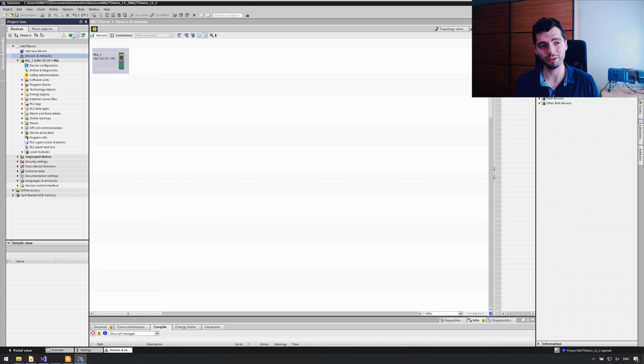But sometimes you will find this icon green with a tiny blue refresh icon. This means that someone made some changes on the project server and your version is no longer up to date, and you should pull these changes down. There's another state which is a yellow icon, and the yellow icon means that someone locked the server. I think there is also a padlock, but I'm not sure. So they can either be maybe in the exclusive engineering mode, or they can be in the server project view. Regardless, it means that you will not be able to push any changes to the server yourself.